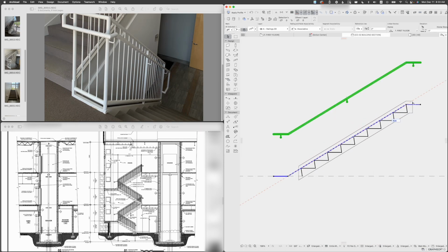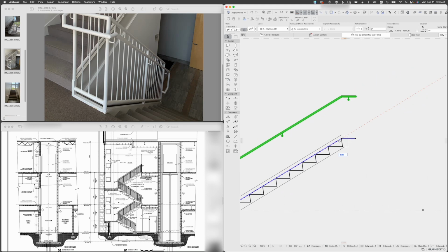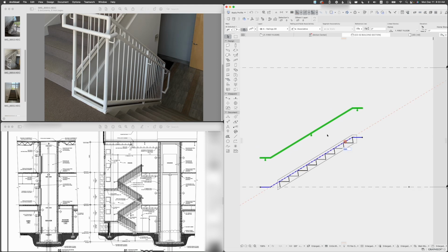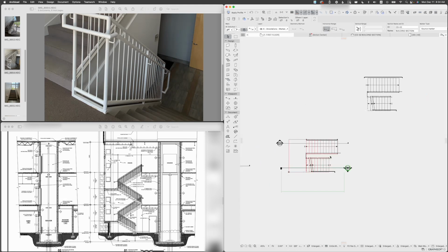And remember, we must continue the handrail down to the floor level and then extend by, I believe, 12 inches. Yeah, 1 foot. And here we have to stop it at the nosing here, and then we have 12 inches extension here. So let's go to the other section.